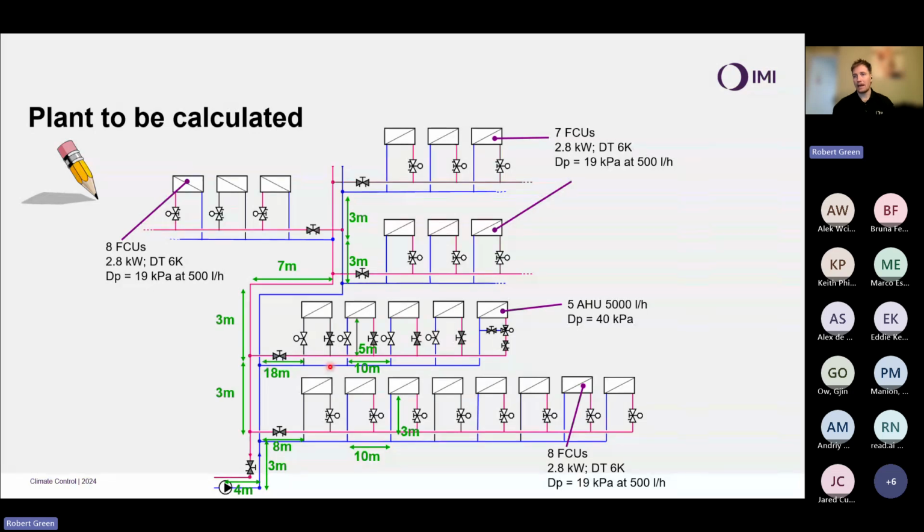To select a balancing valve appropriately, we need to know how much differential pressure it needs to remove. So we need to know the imbalance at design conditions to size that valve. If I want to size a control valve, I need to know the differential pressure variations on that control valve so I can size for a good authority. Without that pipework information, I'd be working blind.